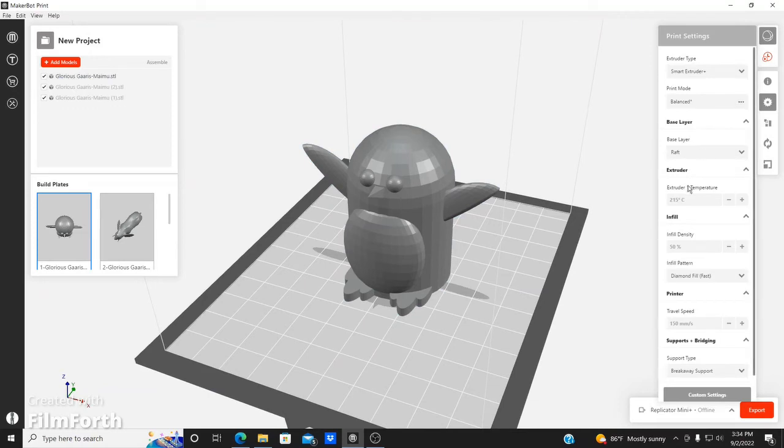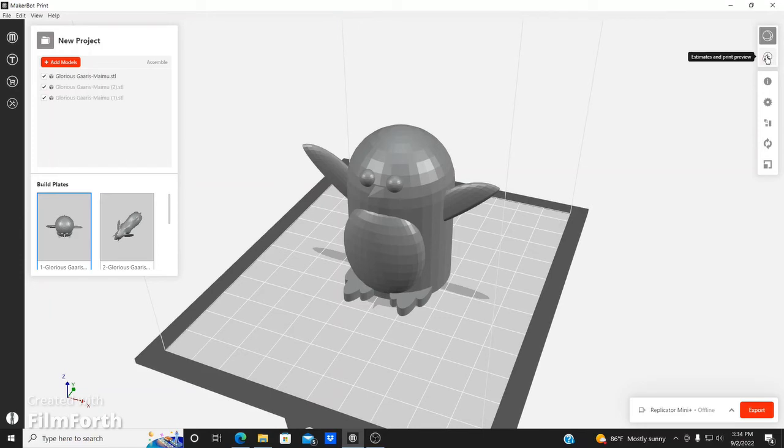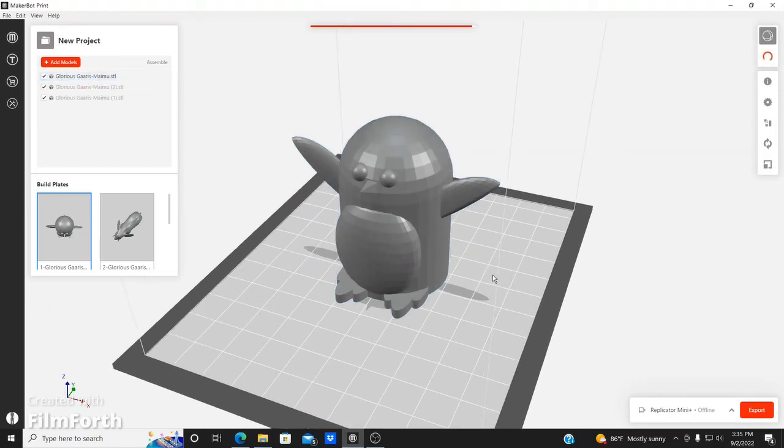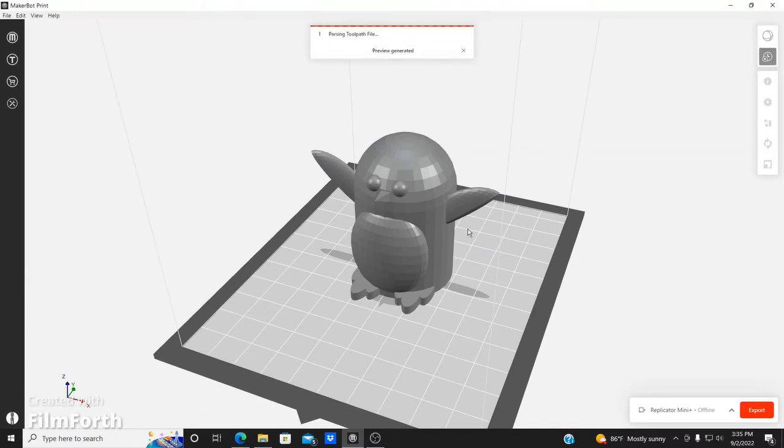If I change over here in the settings, I'm going to change this to 10%, enter, and then I'm going to change my raft to the brim and padded base. Then we'll see. We can generate the preview and look at the percentage. Look how far the loading bar is, and look, it goes three times faster because we added too much infill, and that's a little too sturdy for this guy. I would not worry about this one, because you just want a quick print right away.